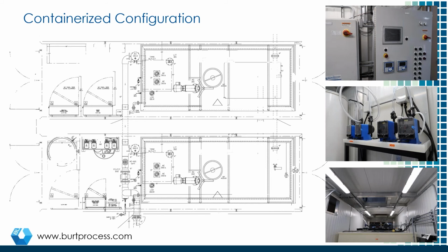And then very often you'll have a separate power feed for the environmental controls. One of the reasons to really do that is so that if you have any kind of an issue within the system and you hit the e-stop button or shut the system down, you don't actually shut down the environmental conditions inside of the building. In that case, you're only shutting down the actual processes inside of the building as well.